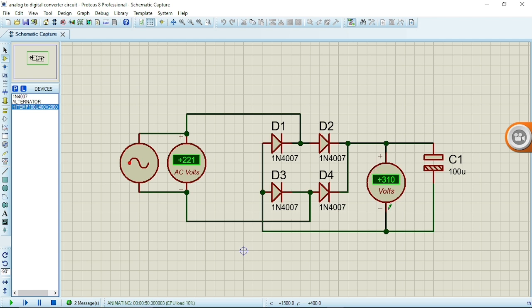So we are going to try to reduce this voltage to an acceptable voltage for our IC, and I believe the highest voltage the LM358 can tolerate is 5 volts. So I will be assuming that 5 volts is the highest voltage for my LM358. So what I'm going to be doing right here is make a voltage divider.